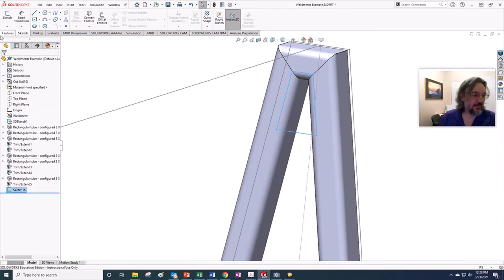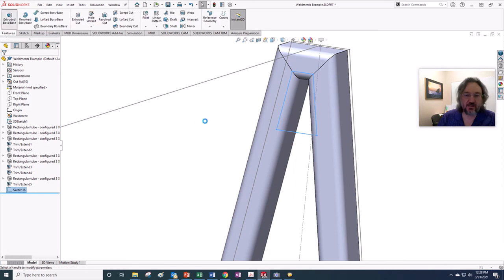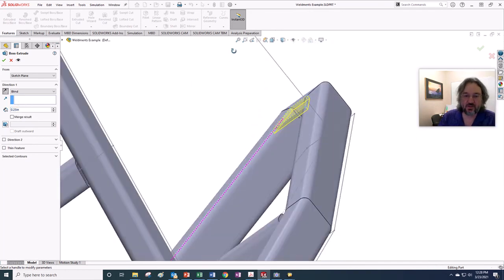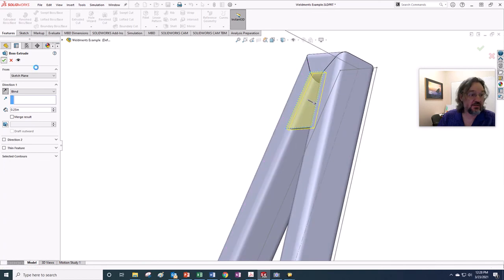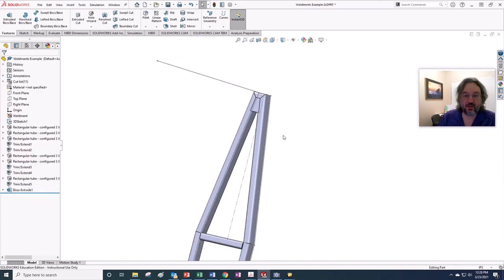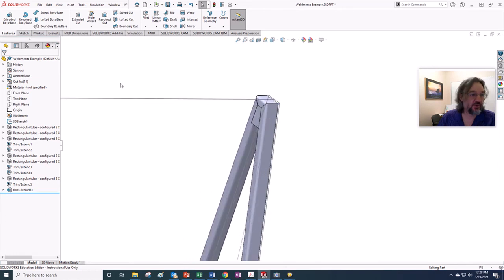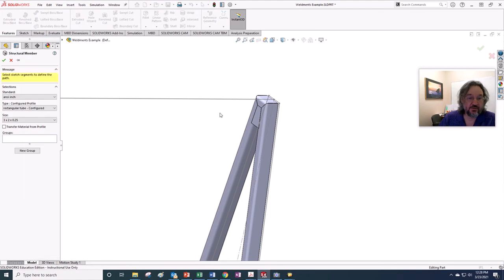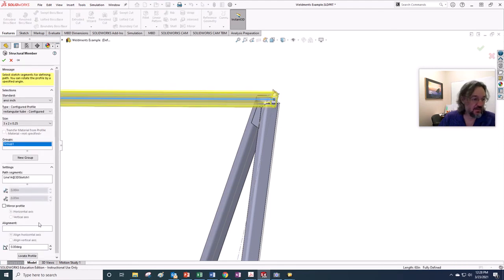And then I might extrude into the thing, and I'm going to extrude the other direction, and I might make this like a 1/4-inch plate, and I'm going to check into the thing, boom, and now I have a place that I could weld to, that I would put onto here. Then if I insert one more weldment into place, I'm going to insert this guy.